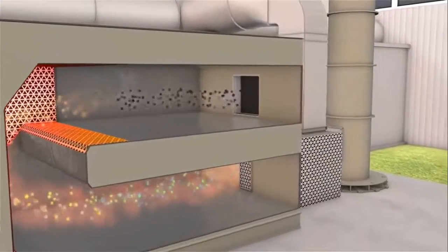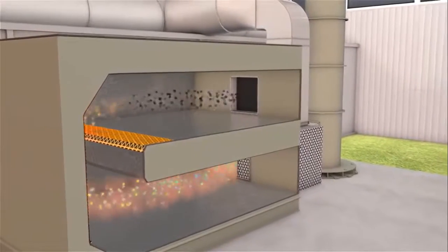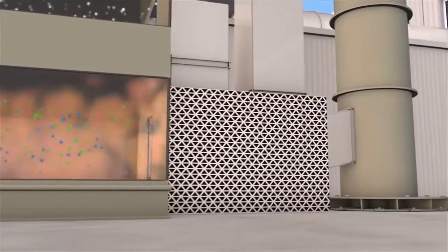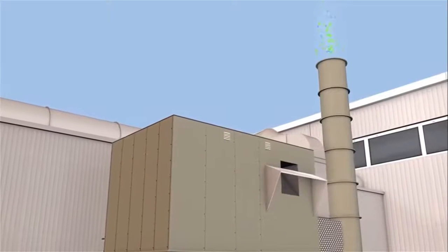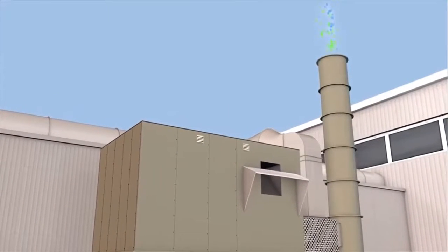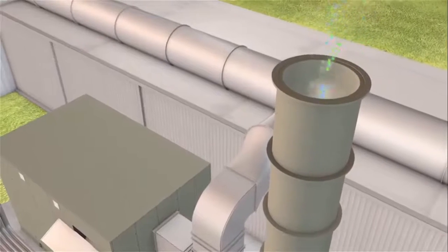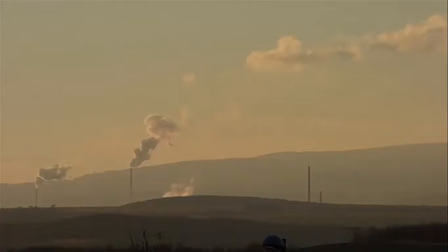Recuperative thermal oxidizers are an alternative to straight thermal oxidation. Adding a heat exchanger allows the system to reuse energy, which helps reduce operating costs. By recovering the thermal energy within the system, operators can minimize the amount of auxiliary fuel needed for the burner, or can even fulfill additional heat energy requirements needed in other facility operations.